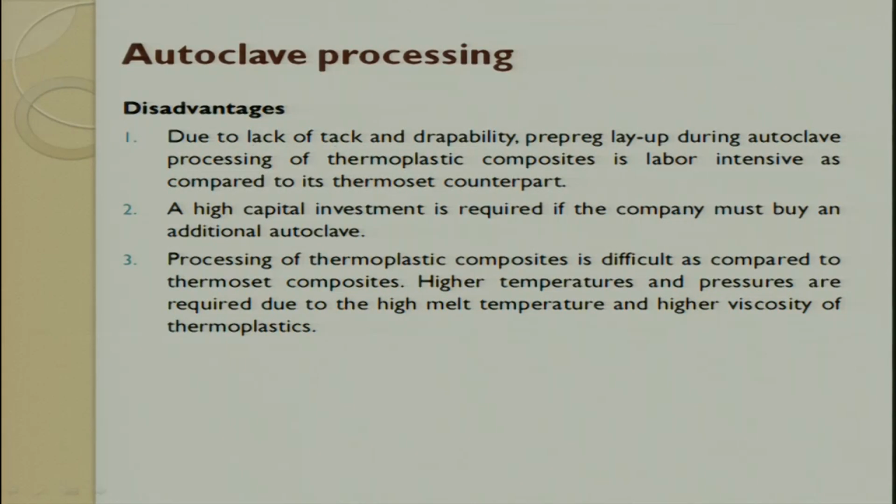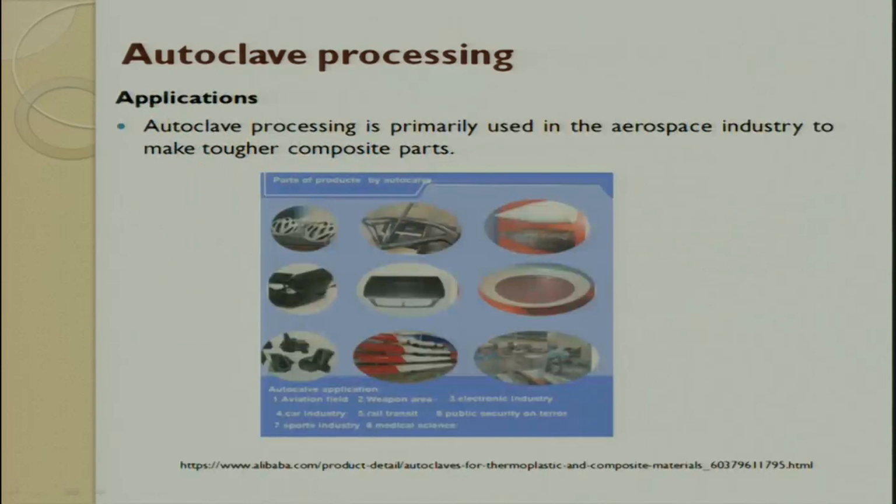So, here as I have told, lack of tack and drapability is there, high capital investment, and the processing of thermoplastic is slightly difficult compared to that of your thermoset. Higher temperature and higher pressures are involved, and there is a component of viscosity which plays a very important role while trying to wet these fibers.